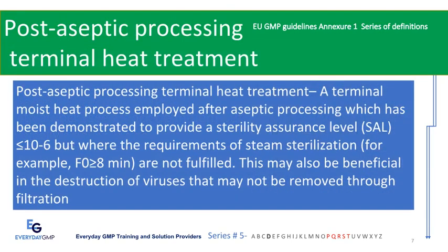Post-aseptic processing terminal heat treatment: a terminal moist heat process employed after aseptic processing which has been demonstrated to provide a sterility assurance level, SAL, of less than or equal to 10⁻⁶, but where the requirements of steam sterilization, for example F0 greater than or equal to 8 minutes, are not fulfilled. This may also be beneficial in the destruction of viruses that may not be removed through filtration.